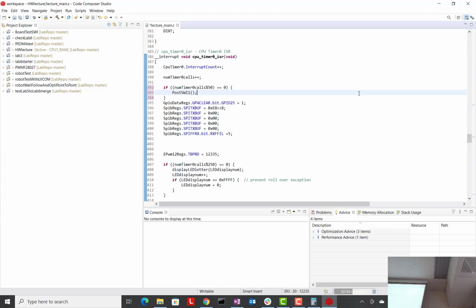The microprocessor that we are using has 2 CPUs, right? Is there any way that both of them can be linked so that whichever is the low priority software or whatever program that we are writing? Yes, each CPU has its own interrupt vector table. And so they both can go on any interrupt. Both can fire on the same interrupt if you want to. So can we run the software interrupt that might take up more time on CPU 2? Yes. With a lot of work, yes.